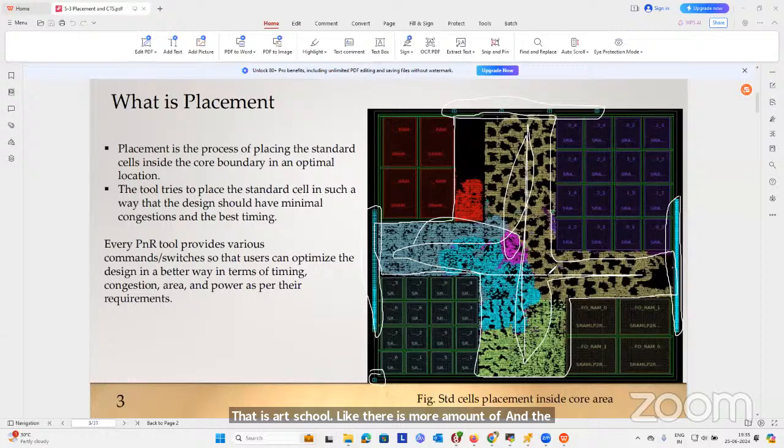The green region is safe, the yellow region like cheetah skin is also safe, and the light ash color region is also safe. The most critical hotspot IR drop regions are red and pink. The tool gives a color-wise symbolic representation for human beings.